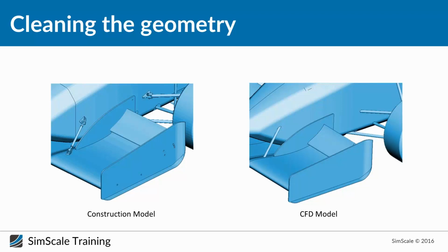that if we want to do simulation with this model, first of all, this model is really detailed. So we need to make sure that we have a really fine mesh to capture all these geometries and all these details in the body, the front wing and this element. First of all, we will have 10 times or more cells invested in this model to really get an accurate simulation.